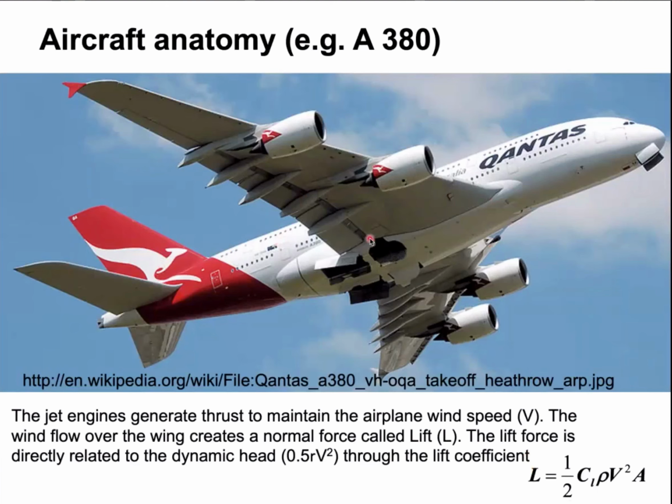If you look at this, this is the fuselage, that's the payload, and these are the wings that are countering the weight. But let's look at it. We have not just one wing. We have these lifting wings, and they also have some little wings connected to them at the trailing edge. There's a little triangular wing at the tip. There is the elevator right here, which is also another wing. You have the rudder, which also has a little control surface over it.